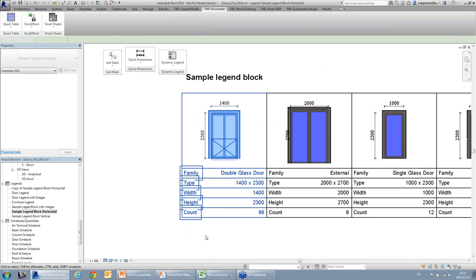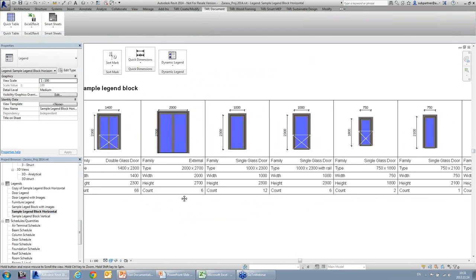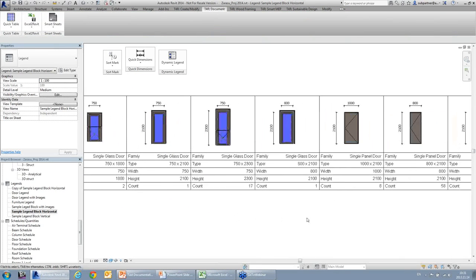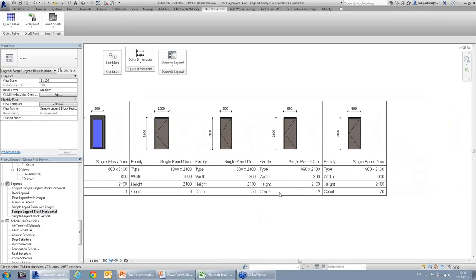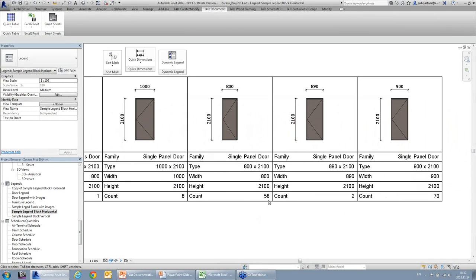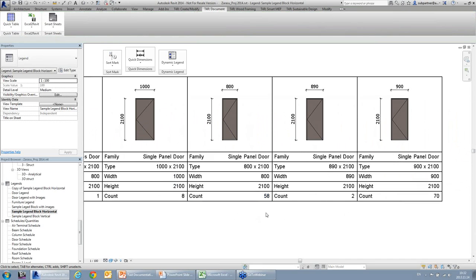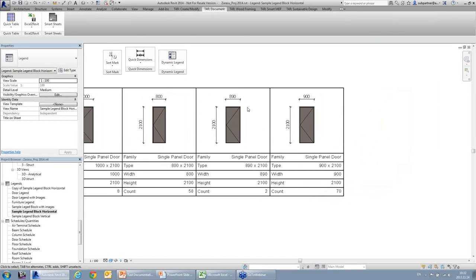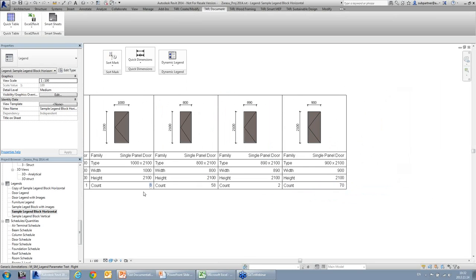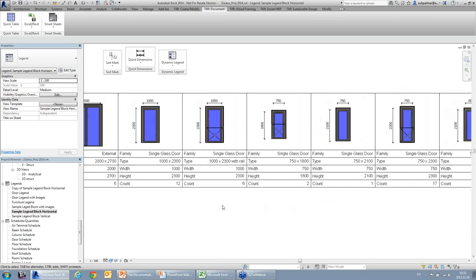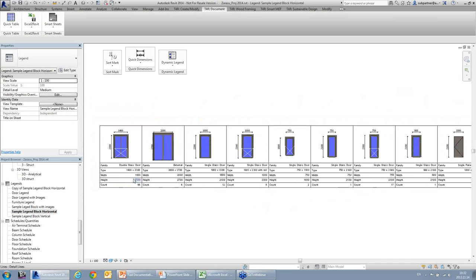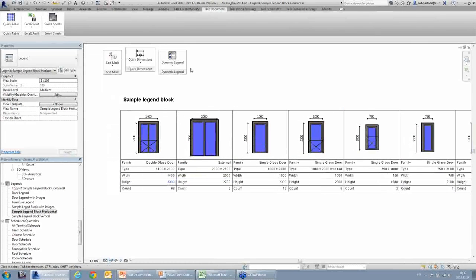After pressing OK, the tool will create a door legend with all those values and parameters. In the end, you will see a count of elements that are used right now in the project, and the dimensions will be automatically changed. Anytime you can come back, if you are not satisfied with the data, into Create Edit Legend.